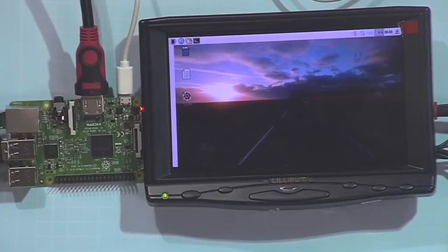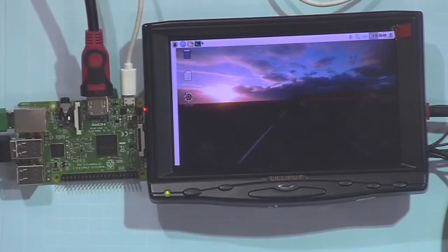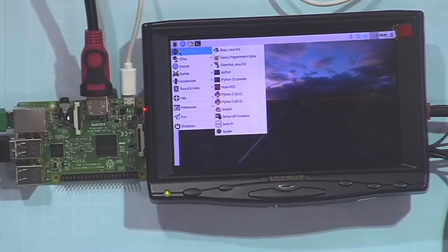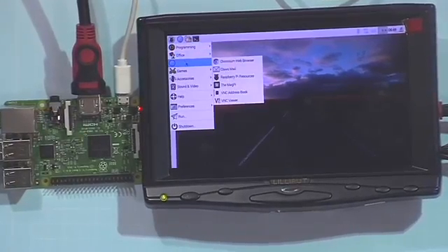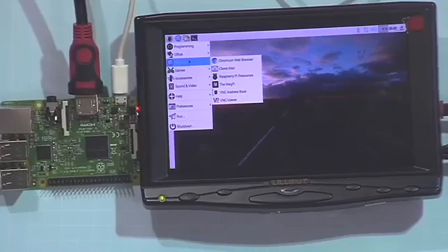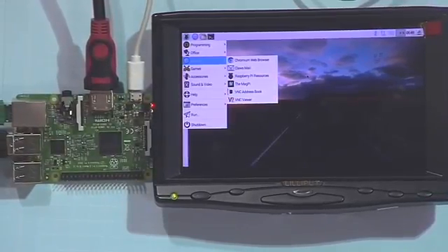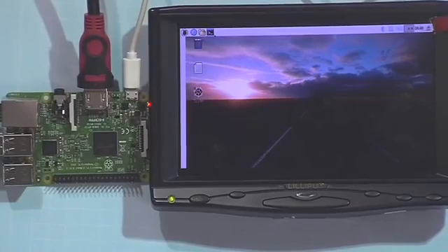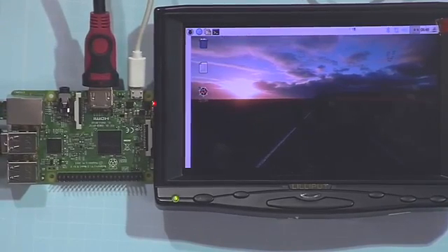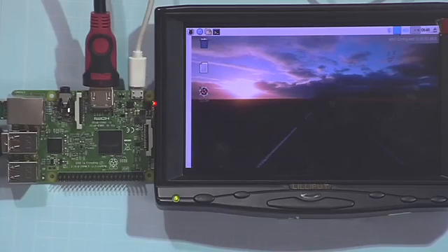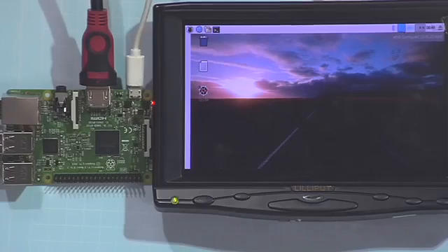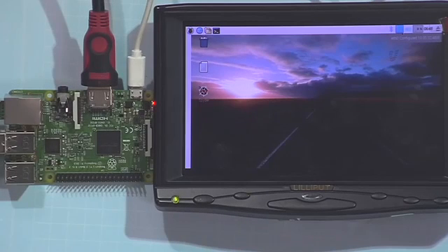Just like the screenshot in the previous slide, you have got one terminal, you have got a start menu option, you can access various programming languages, you can access internet options, you have got options for mail, you have got options for other things. You can also set up a VNC server or VNC viewer on Raspberry Pi so that you can remotely access the user interface on the network. Once the Ethernet cable has been plugged, see this Ethernet has been plugged, so it is showing one IP. This IP will be required to remotely access your Raspberry Pi from your PC.